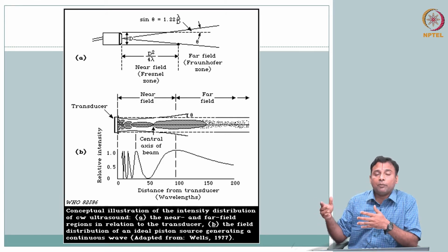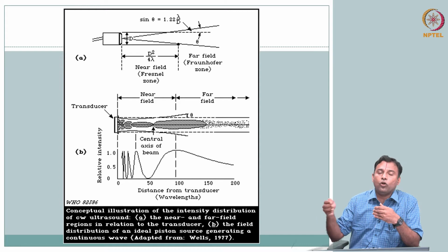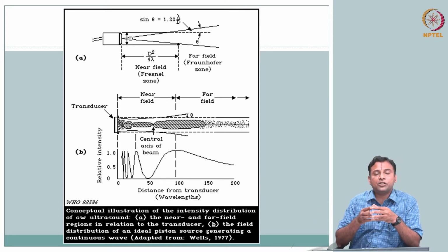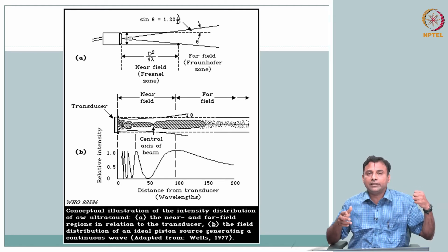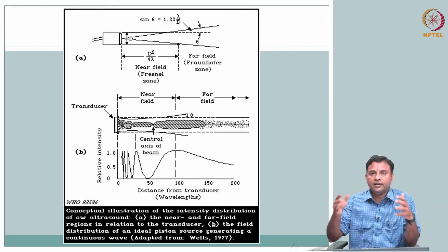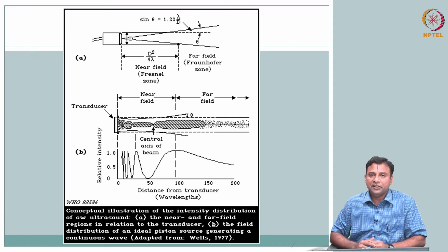So, when you have the pulse that goes in, it bounces back. We saw all the properties about the reflectivity, right, impedance mismatch. So, a portion of the signal or the echo of the signal that you sent comes back, and the same transducer, the piezoelectric crystal, when it is hit with a pressure wave, gives you a voltage waveform, and that voltage waveform is taken and processed further, and you get all the image display, signal processing, put them together, organize in an image and display.